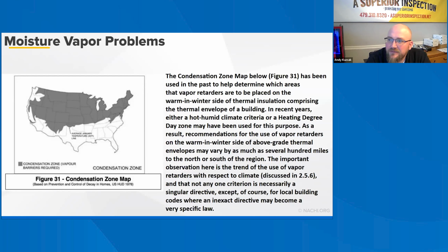From a moisture perspective, very low indoor relative humidity levels are helpful to control condensation and related problems. But other important factors that actually require some minimum level of indoor relative humidity to be maintained must also be considered. These include a minimum humidity level to keep occupants comfortable, which is approximately 25%, minimum humidity to keep wood finishes and furniture from drying out, and for homeowners with special needs for higher indoor humidity. When interior relative humidity levels are a concern, whole house and spot ventilation to the dry outdoor air can be installed, and ventilation controls that automate spot exhaust can be added.